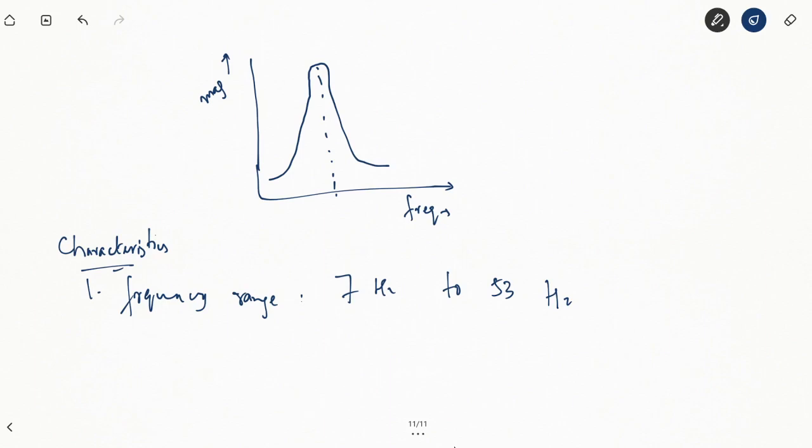This is an indicating device wherein our reeds will be vibrating at their natural frequency of oscillation when attracted to the electromagnet, but the particular reed that vibrates the most does so because it is in resonance with twice the supply frequency.